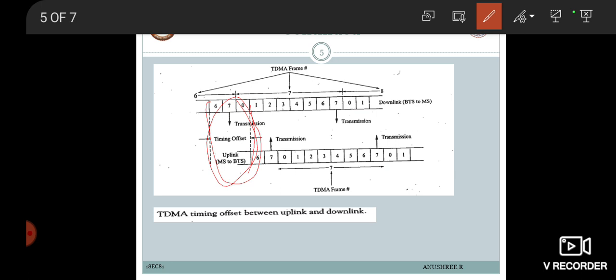The purpose of this delay is so that the same time slot may be used on both the downlink and the uplink radio paths without the need for the mobile station to receive and transmit at the same time. This extends mobile battery life, and it also makes it easier for the mobile's hardware to implement the radio frequency operations needed for proper system functioning.